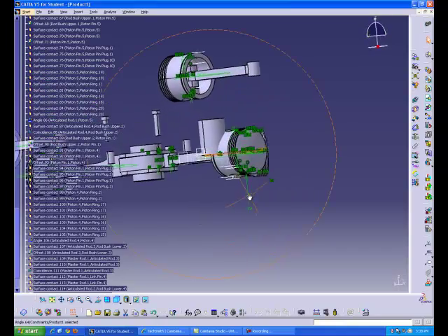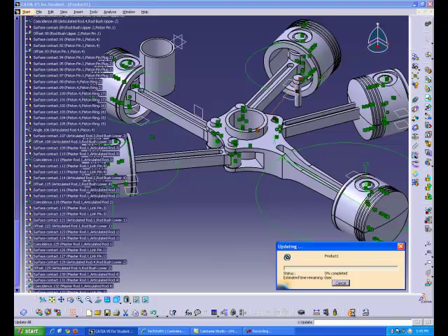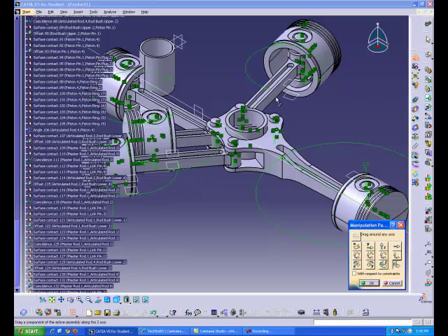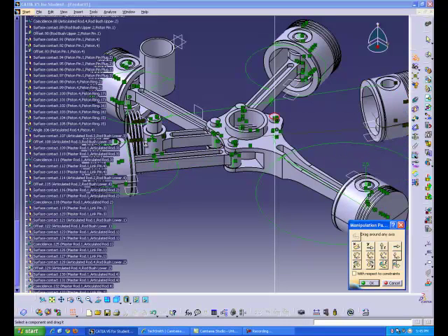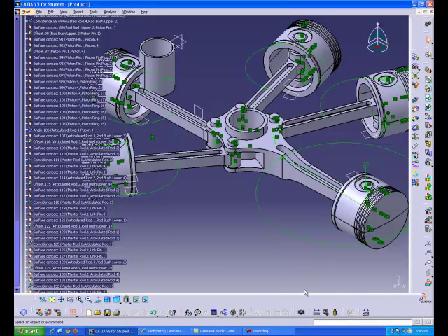Connecting all of the articulated rods to the master rod is the same. So we're going to skip over that and get to this part where if you click update, the articulated rod goes through the master rod. In order to fix this, just use the manipulation button and click the axis of the link pin and rotate the articulated rod around in a circle. Select OK and select update and it should work.